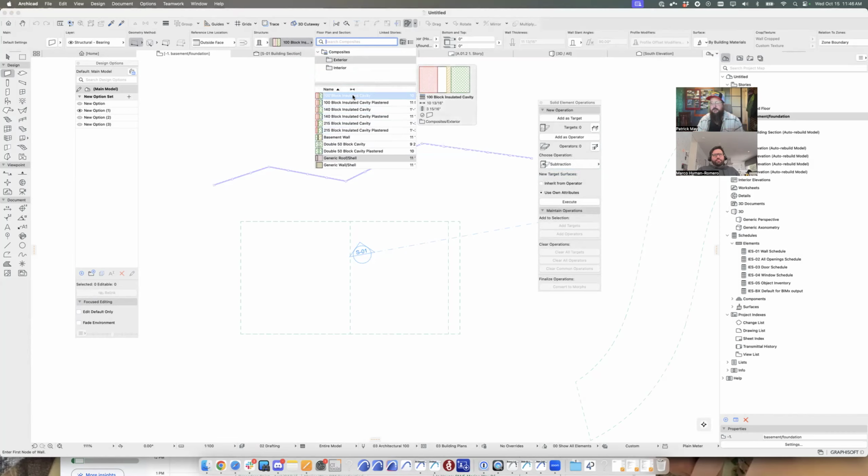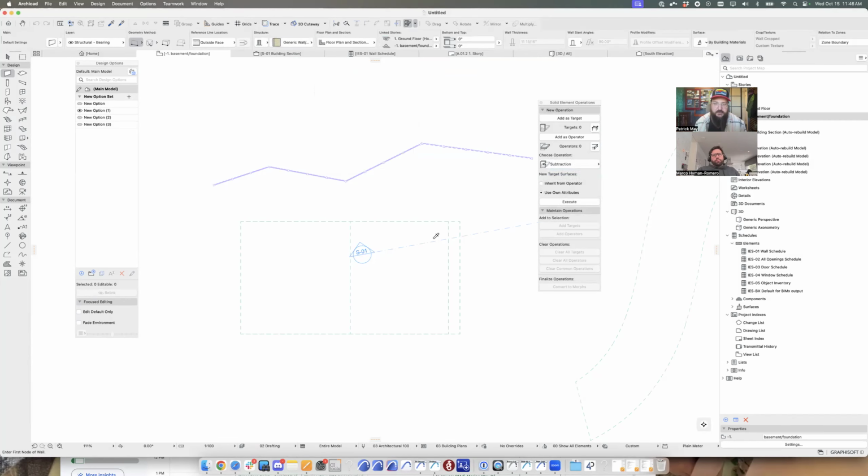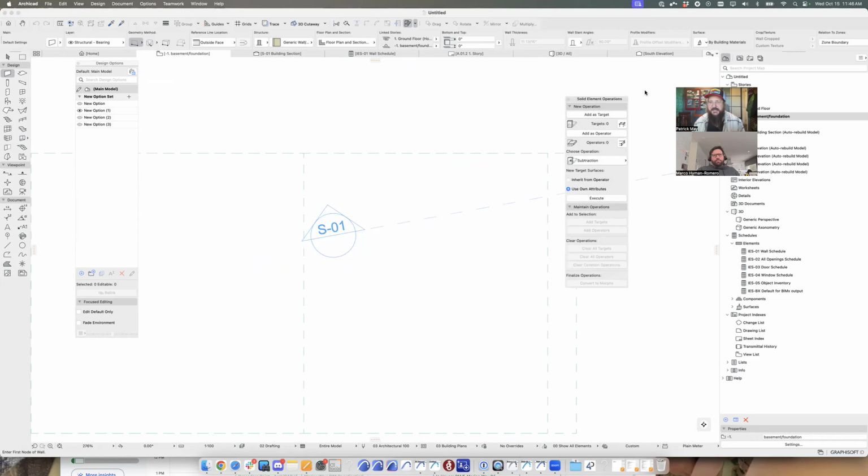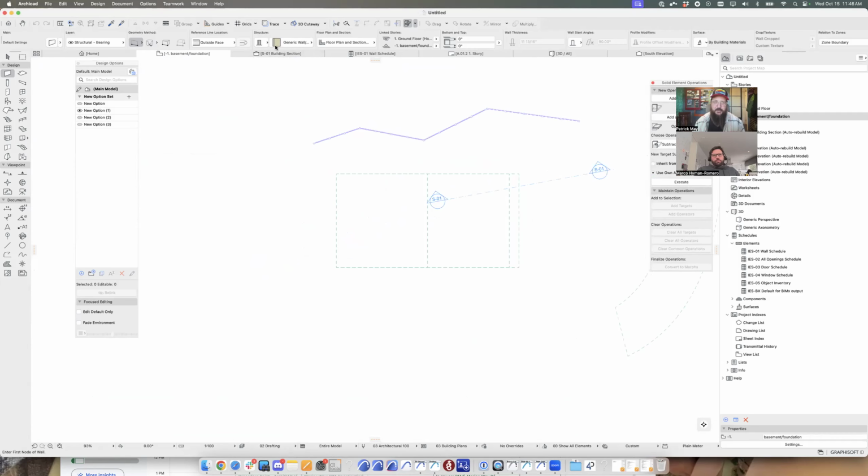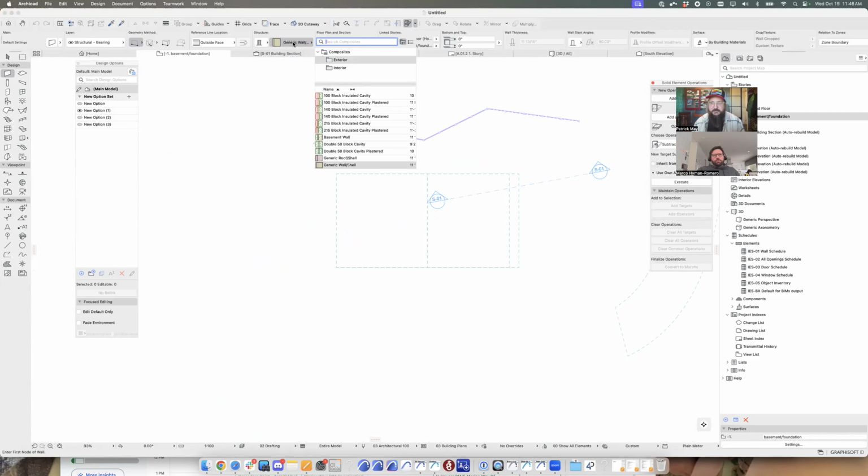But generally speaking, I would want an 8-inch concrete stem wall or a 10-inch concrete stem wall as a composite so that I get global control over my stem wall thicknesses, so that I don't have to go through and pick out all of my 8-inch walls and make them 10-inch when I need to change them. A lot of the projects I work on might go from an 8-inch wall, but then the engineer says, well, it's only one story, let's drop that to 6 inches. Save ourselves a few thousand dollars to avoid being able to do remodels in the future. So that happens all the time. So I want to go globally and say that's no longer an 8-inch wall, it's a 6-inch wall.